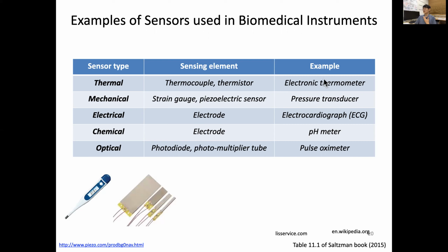An example is a pressure transducer. One type of pressure transducer I actually used is a piezoelectric one, so that we can measure, let's say, gas pressure in a specific vessel. There's a specific gas, and I want to measure the pressure. We have a piezoelectric transducer that measures this pressure and gives rise to a voltage difference that we can measure. So that's another example of a pressure transducer. You see, transduce means converting one type of signal into another form.